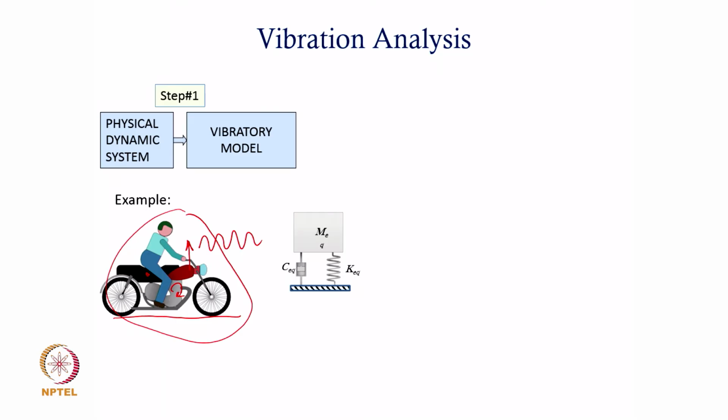So, what I have done is I have presumed that this entire chassis, which is an assemblage of several elements here, can be treated like an inertia, and the mass of this chassis is approximated as m e. Whereas, you may notice here that the wheels are isolated from the chassis, or the chassis in fact gets isolated from the ground by the shock absorber or the isolators, and there are two of them, one on the front side, one on the rear side.